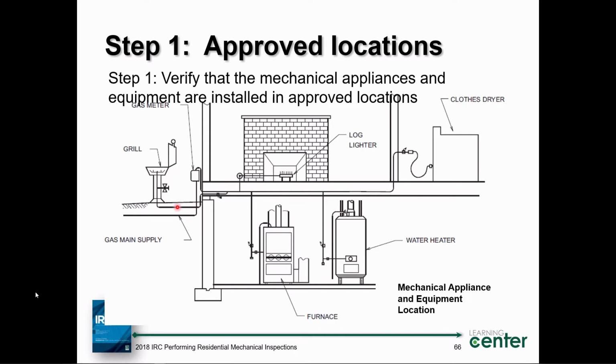When we emerge from the earth, it's got to transition from plastic to metal piping. We call this anodeless risers. These are devices, piping type of equipment that we use to transition from plastic polyethylene pipe to metal pipe when we emerge above ground. Okay, so that's a simple little gas piping drawing. Any plumber, any pipe fitter, any homeowner is capable of drawing a nice little cartoon picture like this, aren't they? Sure. Now ask yourself, can your inspector go out and inspect this gas piping system as it's drawing?